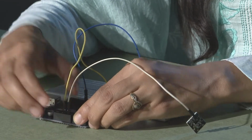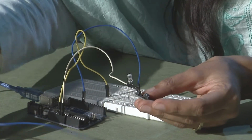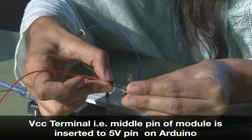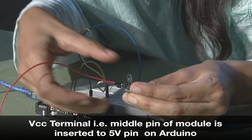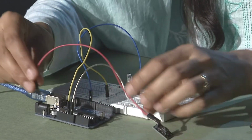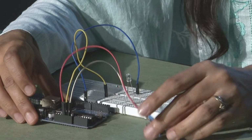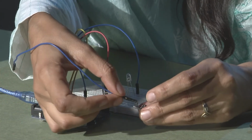So this is the first connection I have made. Secondly, I can pick my VCC terminal, which is the middle one. Let me insert my wire in this, and as soon as this connection is ready, we can use this 5 volt on the other side of Arduino. The second connection is also ready, and now we can pick up the signal terminal.